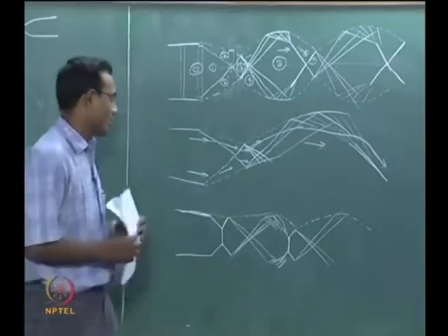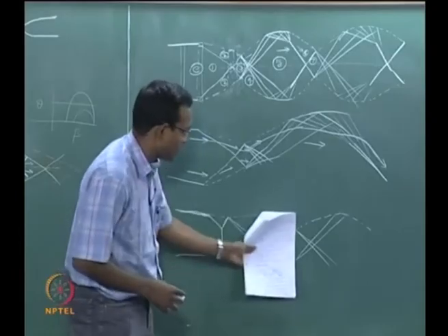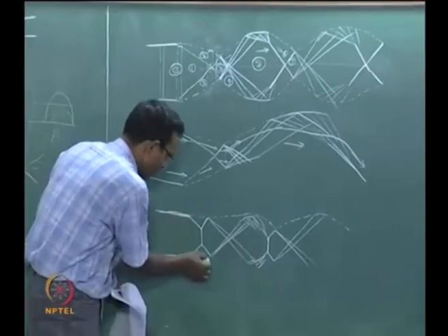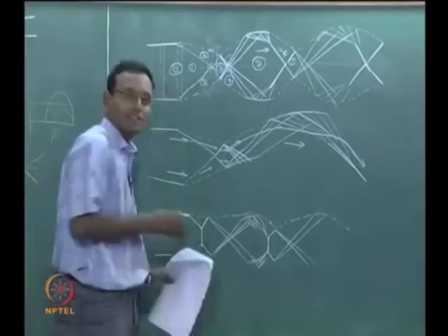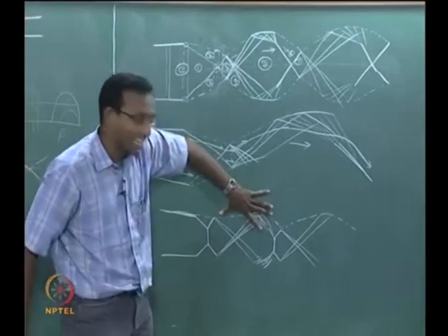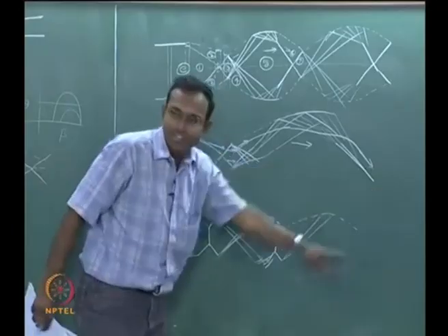Okay. So if you look at it again, starting from expansion till the shock, the whole sequence repeats after that. Only thing that does not repeat is the first shock portion. This particular thing is called the expansion shock cell. Okay, the same structure repeats again and again. They call it the shock cells.